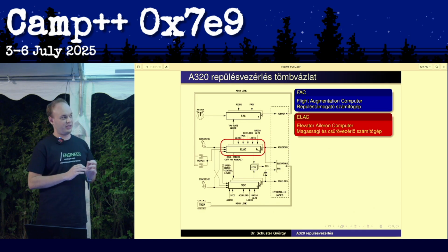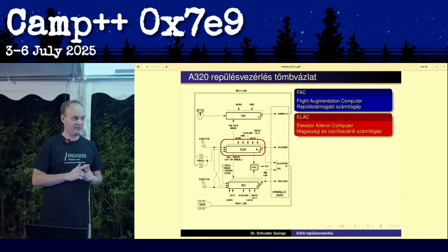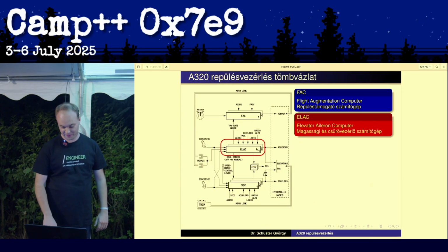So typically you would use something like an open drain output to connect the two outputs in parallel, and then the safe state has to be the pull down state for the system.